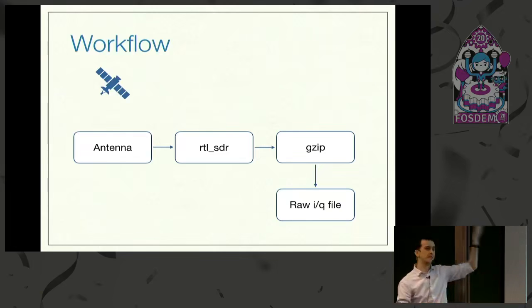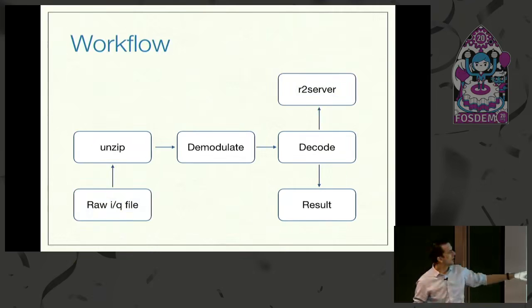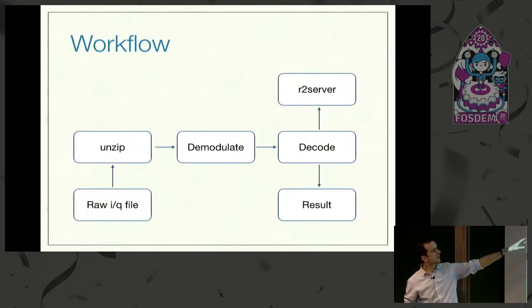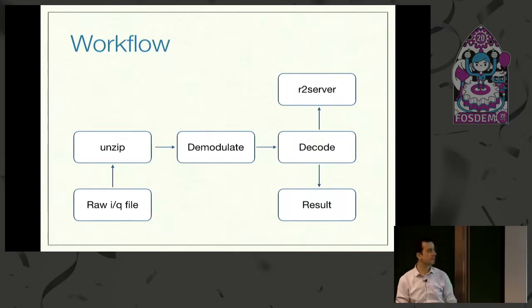When the satellite has left the sky, then the base station should stop the SDR and just execute the next step. And the next step is the following. It reads the data from the disk, demodulates it, decodes it, and saves the result onto disk. And optionally maybe saves it somewhere centrally for aggregation purposes and sharing with the community and the scientists. And this step could be executed concurrently with the first one, so that I could optimize the load. All I have to do is just demodulate and decode the data.